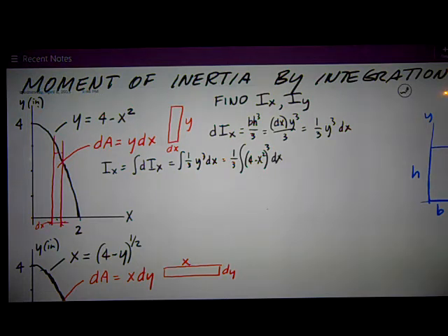So I plug that into my integral calculator, TI-36X Pro or something, and I'm integrating along the x-axis, so from 0 to 2. After a few seconds, it spits out the answer, 19.51. The units are inches to the 4th power. Everything's in inches, so I've got inches cubed, and once I integrate dx, that's also inches, so I get inches to the 4th.